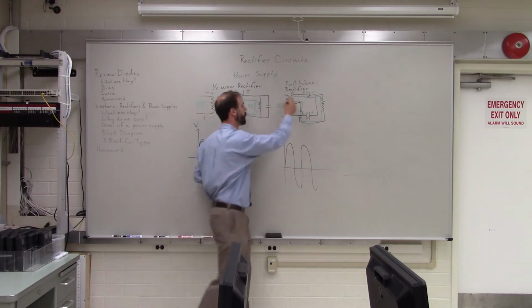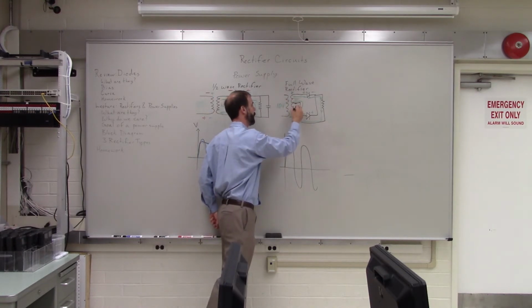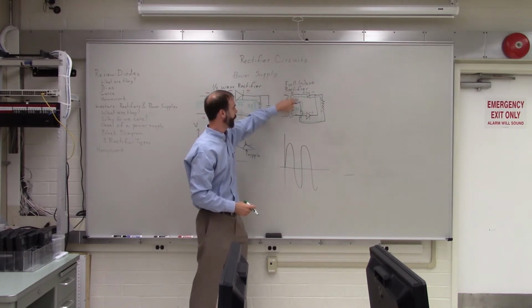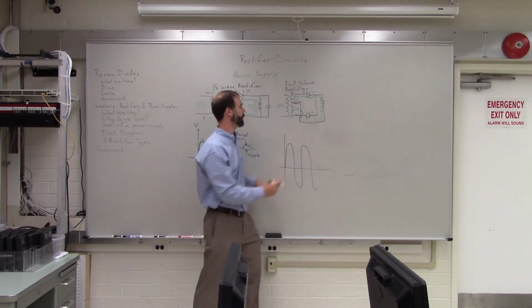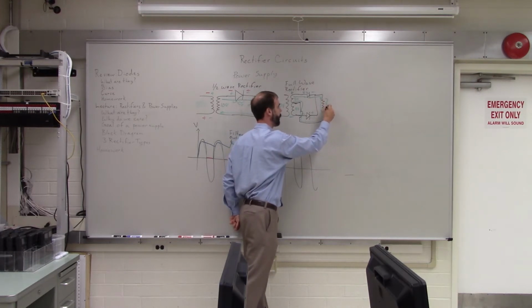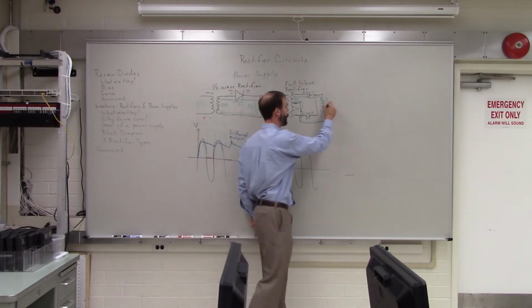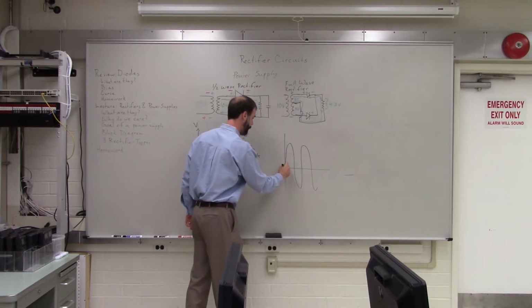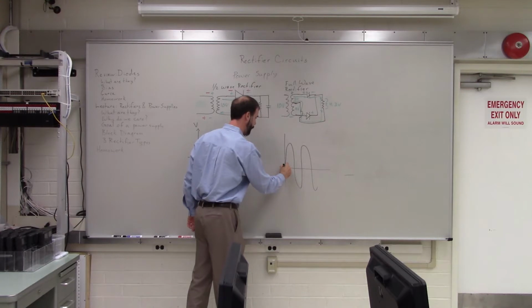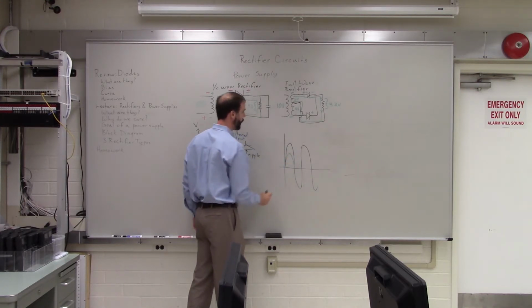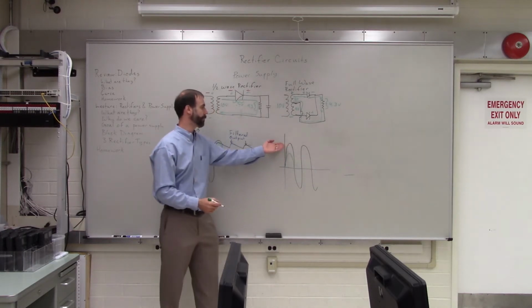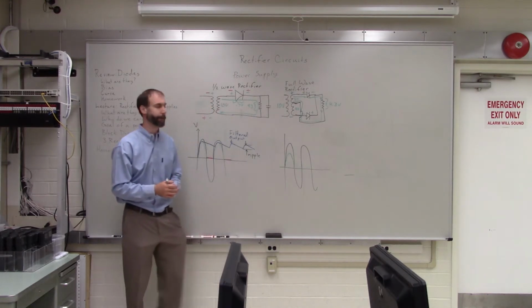So you get 5 volts up there and 5 volts down there. So now we've only got 5 volts to work with and we lose 0.7 volts there. So how much voltage do we have across our load? 4.3. 4.3. Exactly. So that means that our output goes something like that. So it goes positive, but it's less than half of our input. Okay?